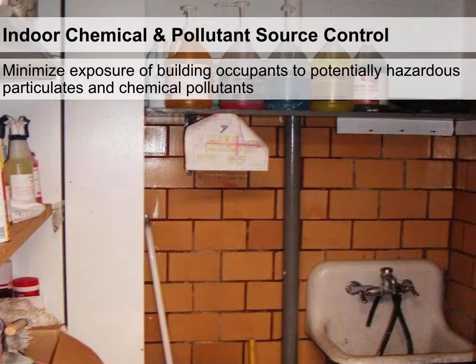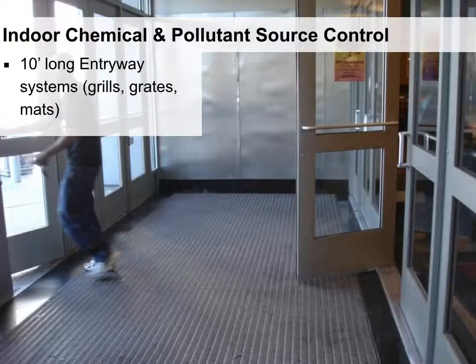So a few other things we should keep in mind are some other sources of indoor air pollution. A lot of times we'll find these in janitor's closets. That's because in a janitor's closet, you may be storing paint, you may be storing chemicals. There are cleaning products that may be off-gassing or that are being mixed. And so, having things like negative pressure and exhausting these rooms, or even using green cleaning products with low VOC emissions can help for that source.